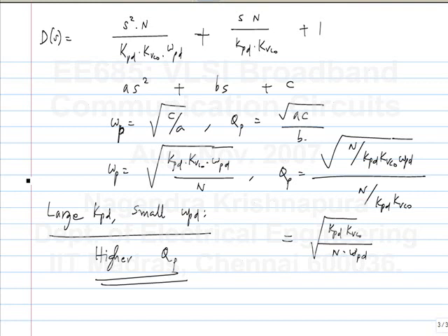So, the idea was good of trying to make KPD high at low frequencies and letting it roll off at high frequencies. But the problem is it becomes a very high Q system and we can't do this. Okay. So, what do we do next? No, N is given by the system, so you don't have freedom to play with N, right? You have to generate a certain output frequency from a certain input frequency. So, N is given to you, and making N large doesn't help also,